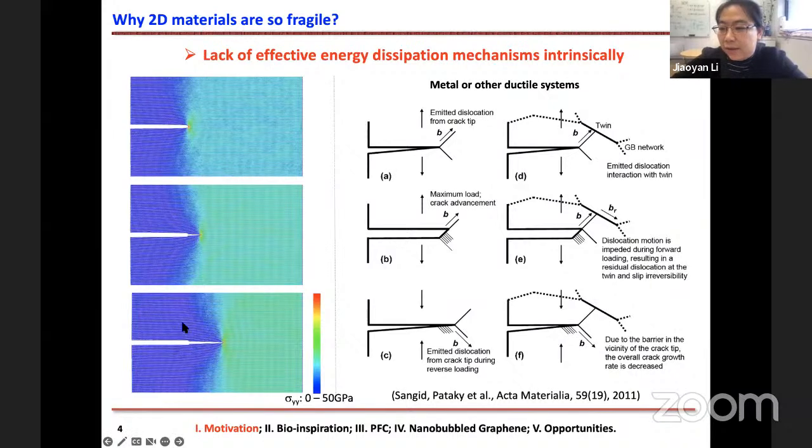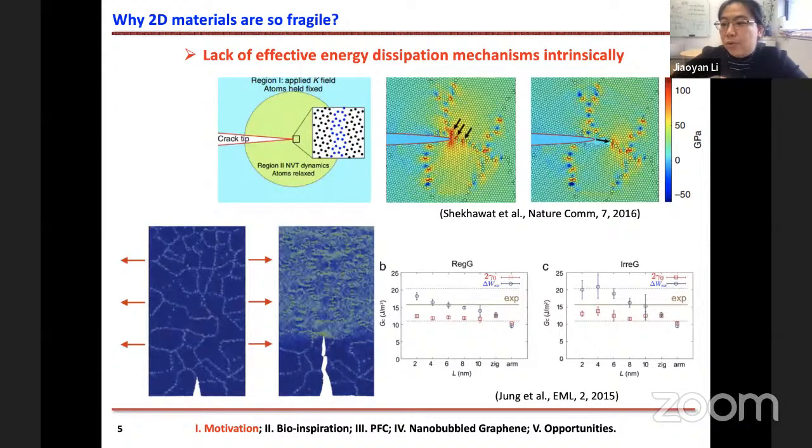And the color here represents the real stress along the loading direction. People were also wondering if the fracture toughness of the polycrystalline system could be higher than the pristine case. The answer, in fact, is yes. The polycrystalline system has intrinsic dislocations as grain boundaries. Therefore, during crack propagation, the intrinsic dislocations can alter the crack path a little bit, as you can see from here. So the crack can propagate along a certain direction of the grain boundary.